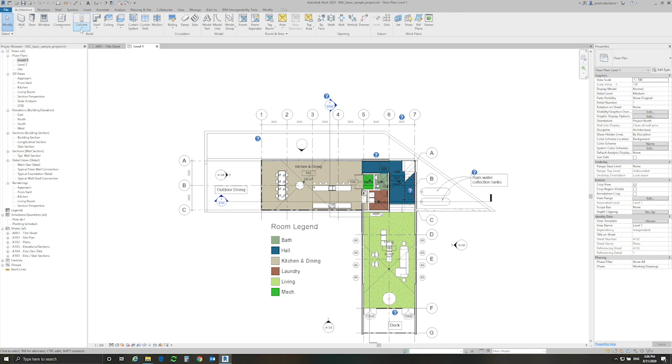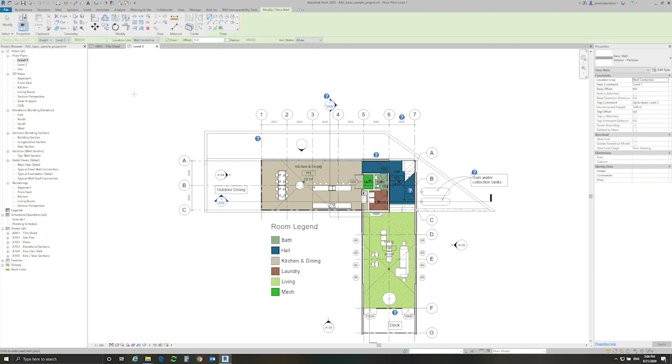Just so you know how that's structured. Now, Revit is a contextual-based software, meaning that elements of the UI are going to change based on what you're doing. So I'm going to show you what I mean by that right now. Let's say I'm creating a wall. So I create a wall, and you can notice that on the top, a lot of stuff just went green.